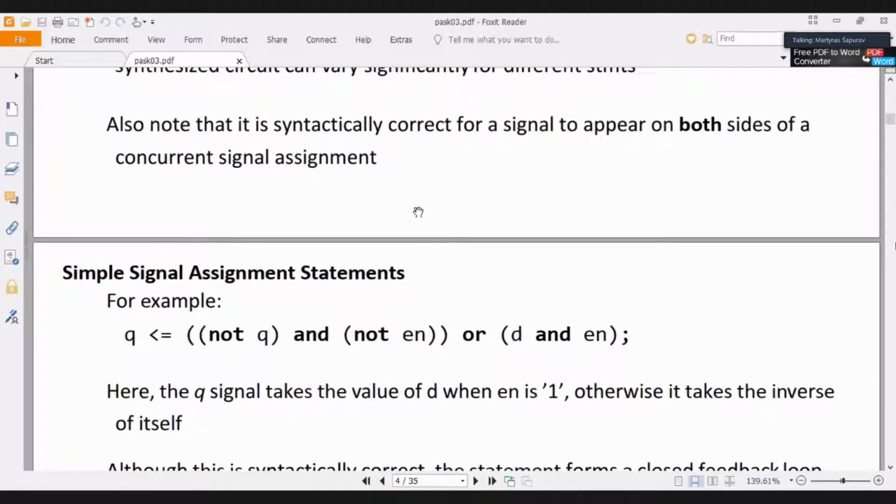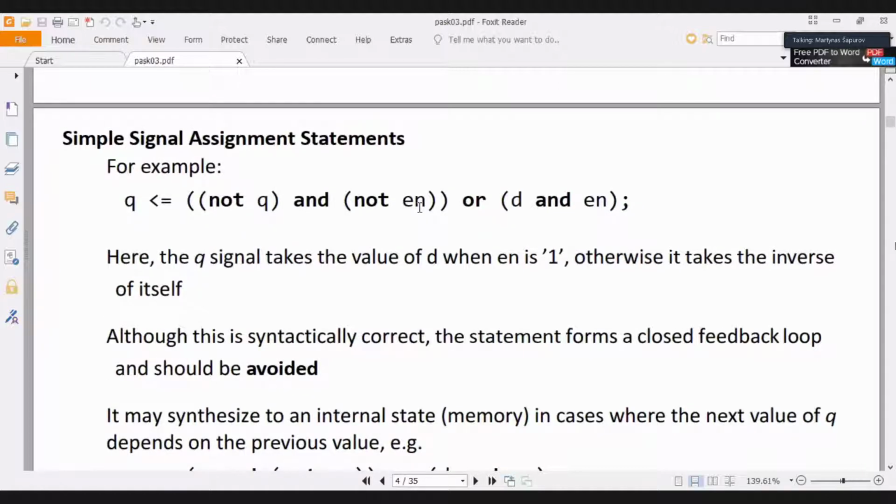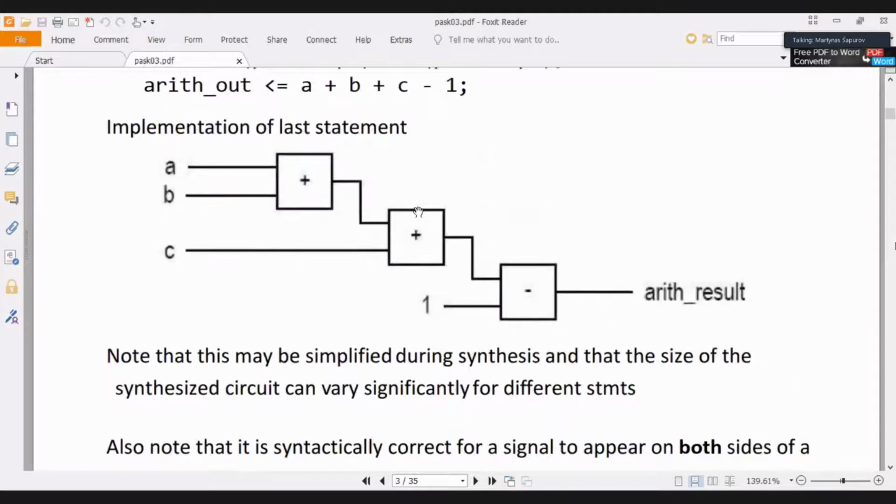You also have to remember about using brackets, as we discussed in the last lecture, that there is a certain execution order also in VHDL. Therefore, if you want to change the order or make your code more readable, you could add additional brackets to specify the sequence. By sequence, I mean that it will depend on which part of your electrical circuit this operator exists.